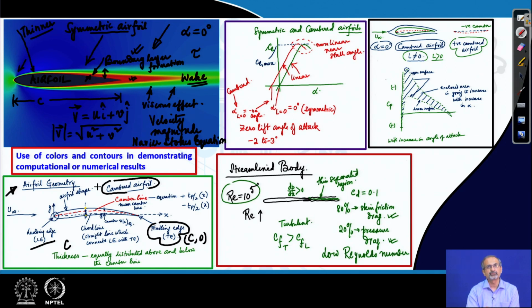While here what we are observing is, we have information about the complete flow field around the airfoil. That means, in all probability we are solving the Navier-Stokes equations, which is not only confined to the viscous regions around the airfoil, but looking at a bigger domain within which the airfoil is placed.